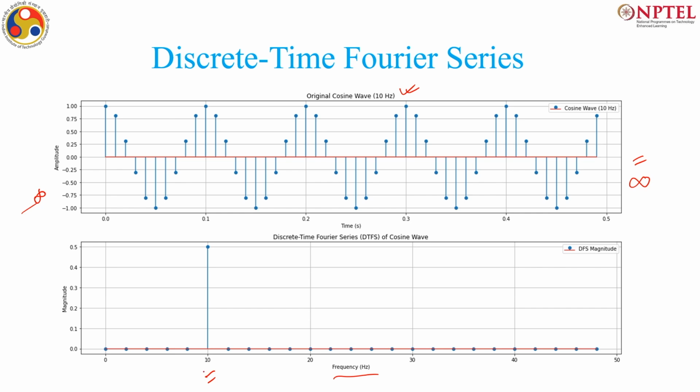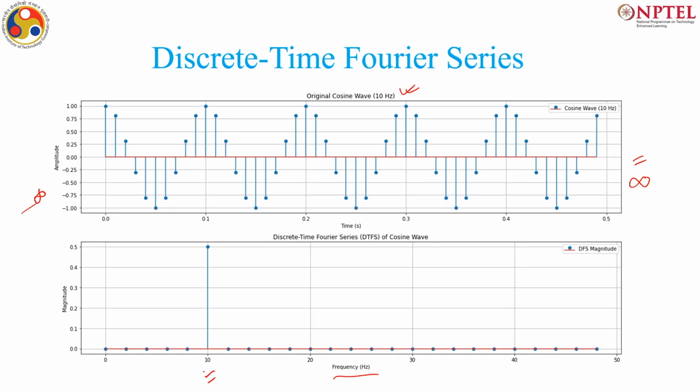One takeaway in this graph is that in the time domain you have to use an infinite number of points, or at minimum the points that contribute to one period, but in the frequency domain you just need that one frequency point, which is 10, describing the signal, and maybe one more point defining the amplitude.